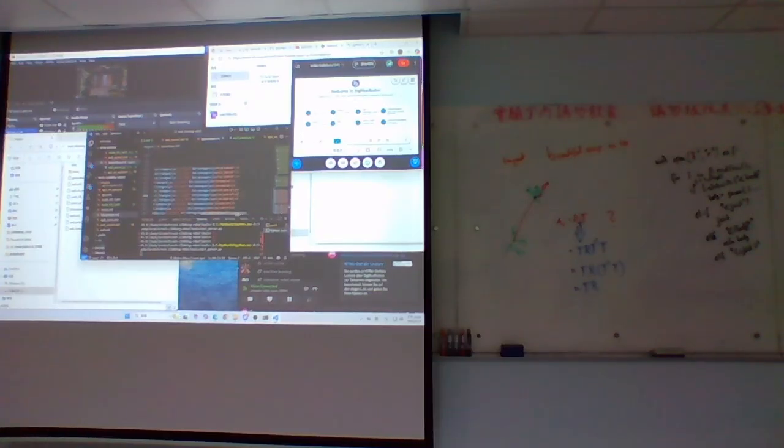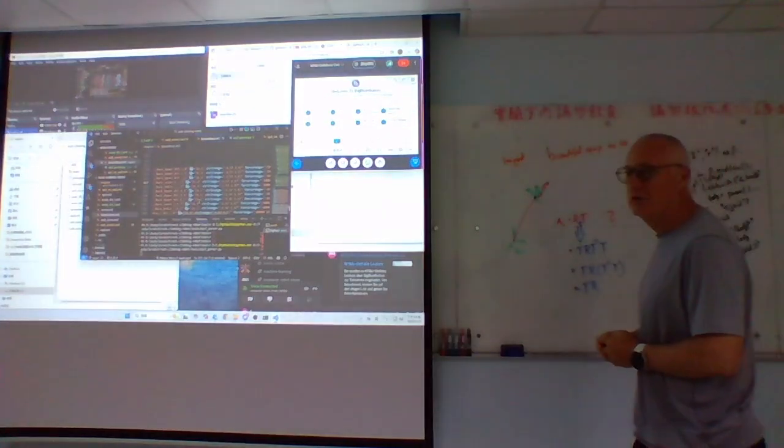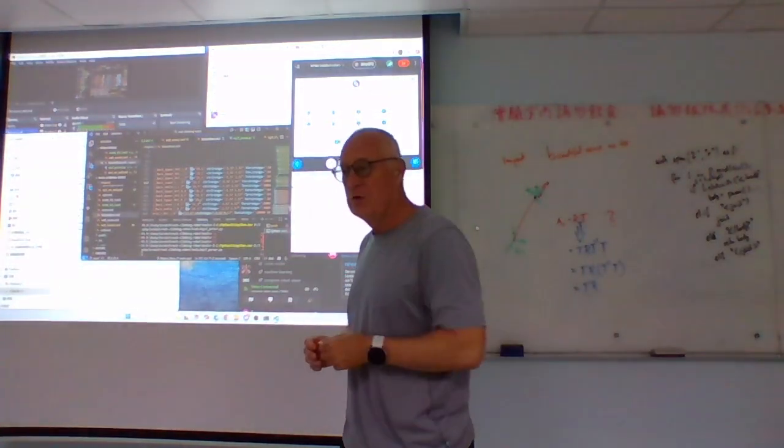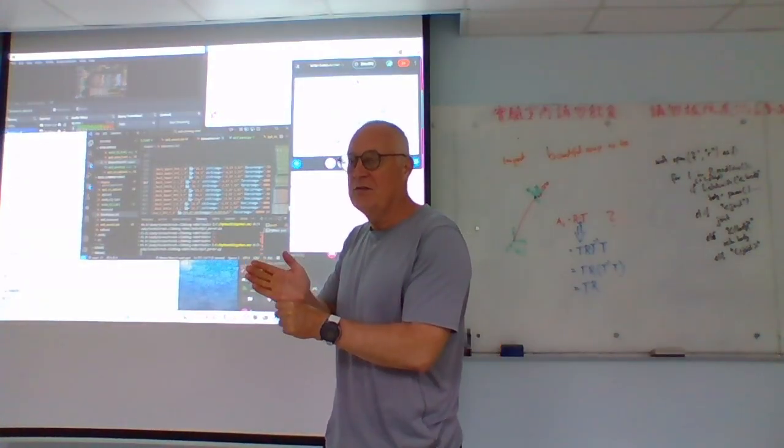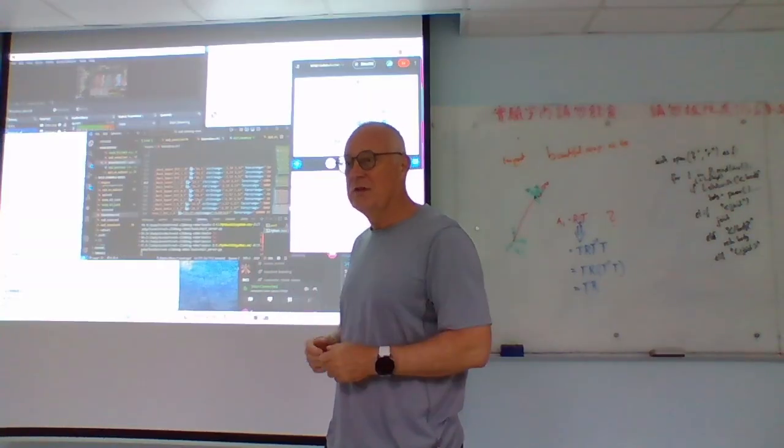here. You can set the KP, KD, and KI gains for the PID controller. Do you need the PID controller? If you have a position control, yes. It depends if you use torque control or position control. I mean PID like for balancing, no, it's different. Yeah, it's different. For the servo motor, right? There is a PD control loop running on the servo motor for each one of these motors. Because you tell it to go to 10 degrees, it needs to have a controller to move it to 10 degrees, right?